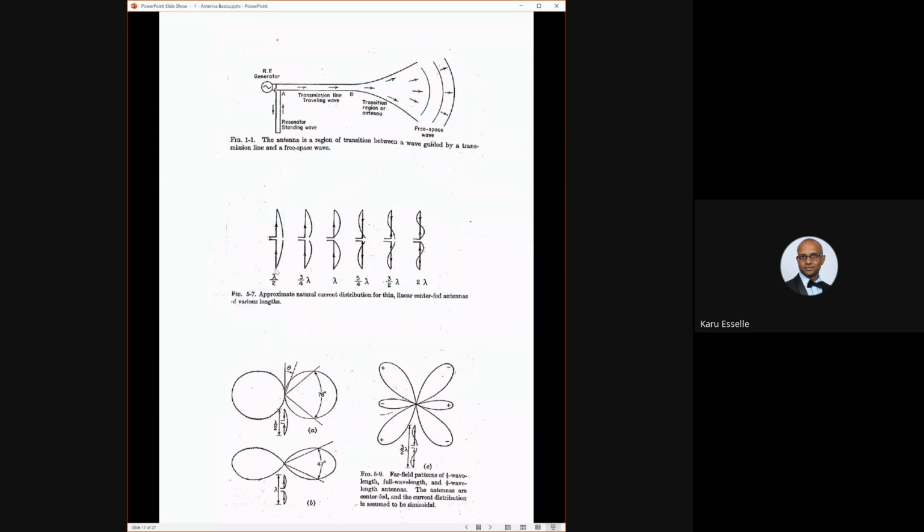When the length of the dipole is half wavelength, lambda divided by 2, that is from here to here, then the current in the middle becomes maximum. The half wave dipole is a very useful antenna, extremely basic but very useful for several reasons. One is its impedance.